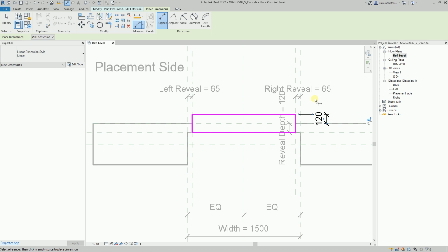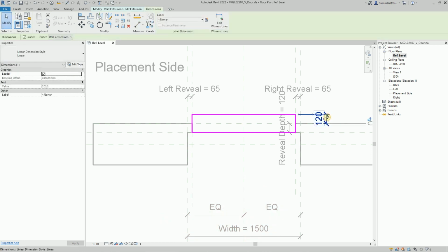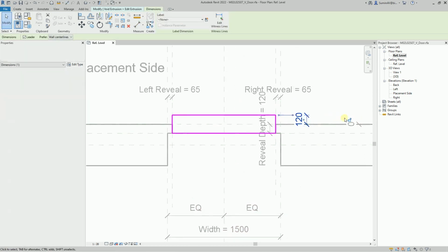Besides the fact that the size can be associated with a parameter, it has also one more interesting property. We can simply select it and close the lock. Such a dependence will mean that the distance between the objects to which the size is attached will always have a constant value, in this case 120 millimeters.